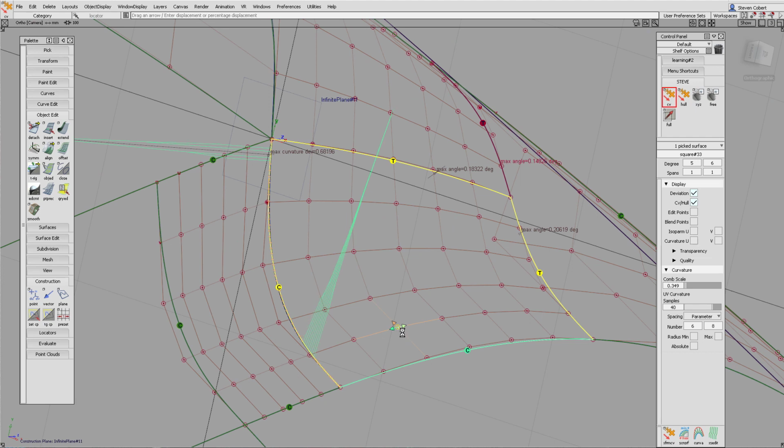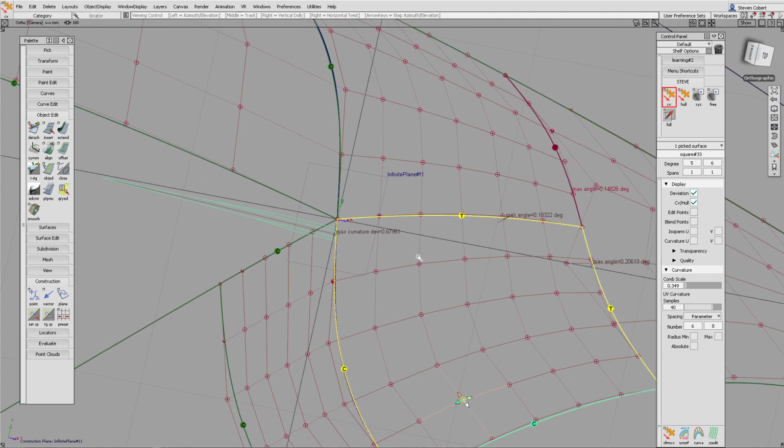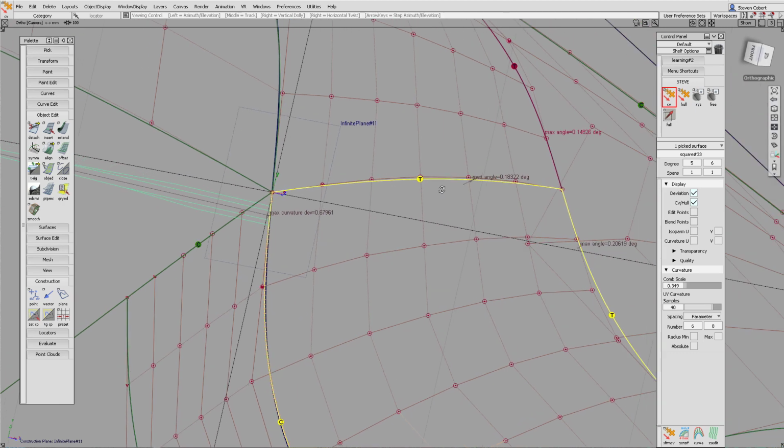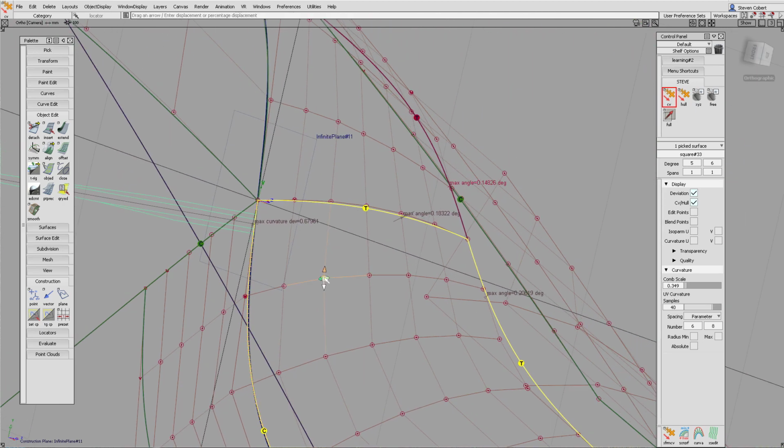And to start with, we're going to just move the CVs only in the Z direction, but you might find that it's better to slide them or move them in the normal direction as well. Above all, what we want is neat CVs. And looking along the ends of the hulls is often a good way of assessing them in 3D.